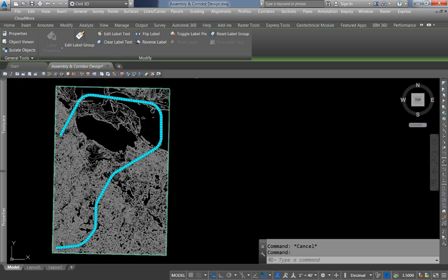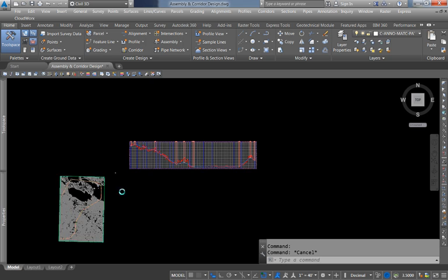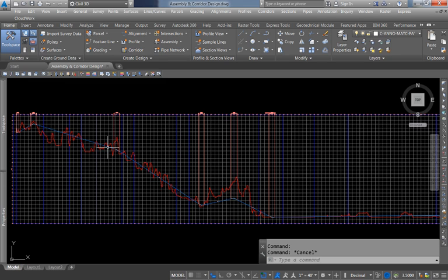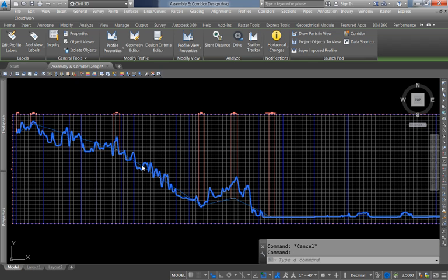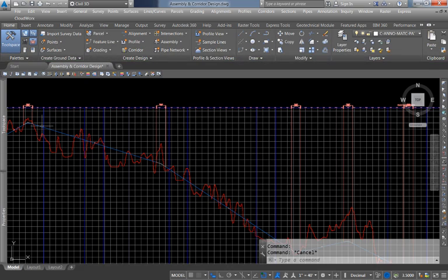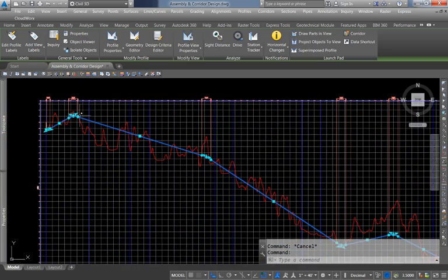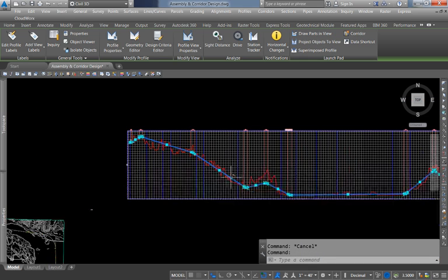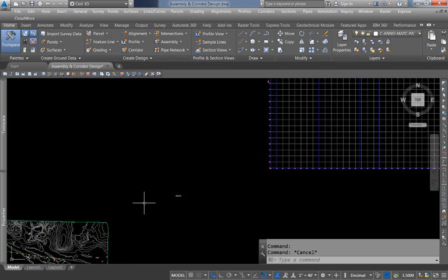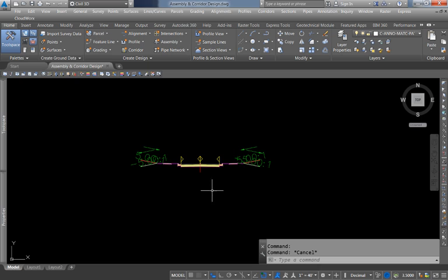It's going to follow this alignment, which we've created from a P-line or polyline object. We need a surface profile. So here we have a surface profile which shows the existing ground elevation as we travel along our alignment. And we've also created a design profile. So this will be the elevation of the ground after we construct our road, or where we want our road to exist. And then we need an assembly, at least one assembly.